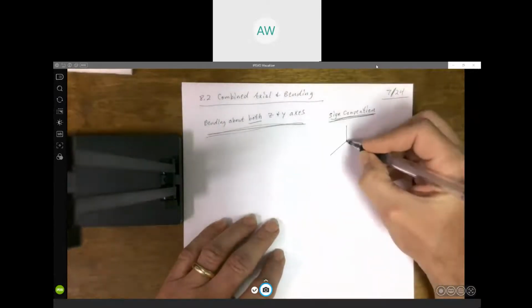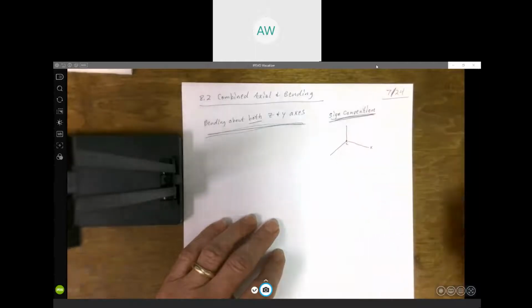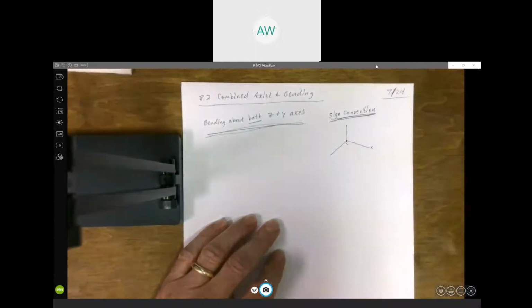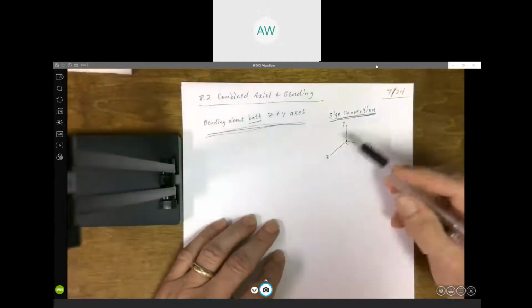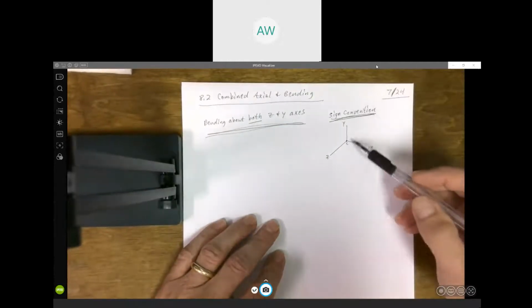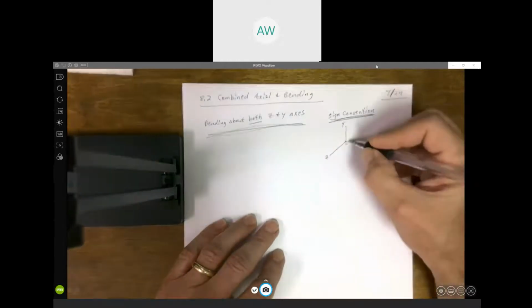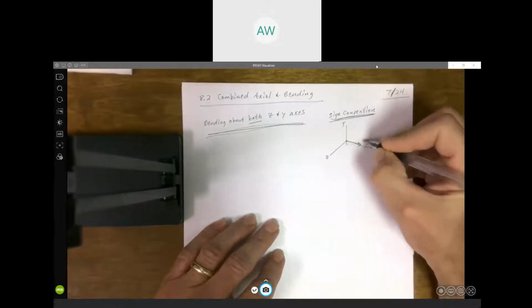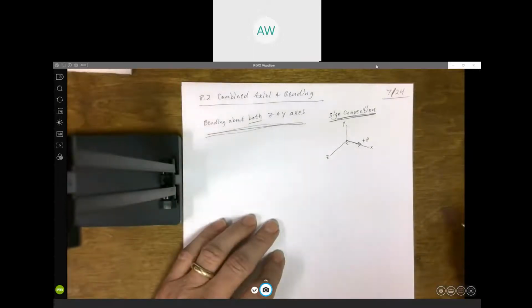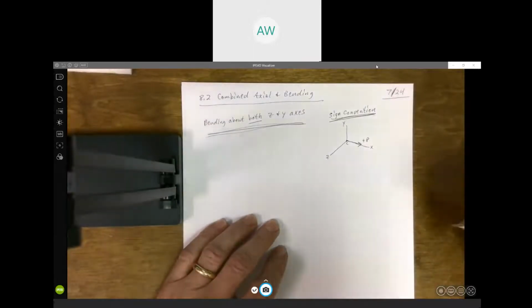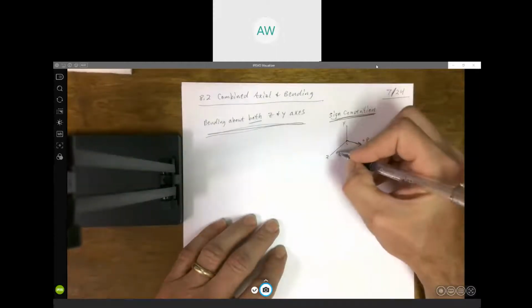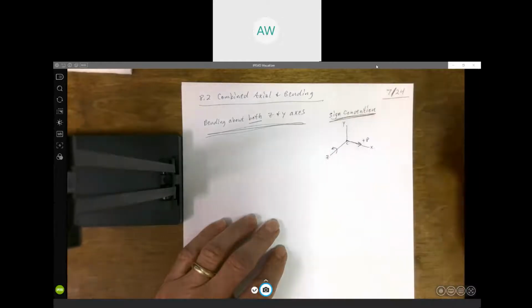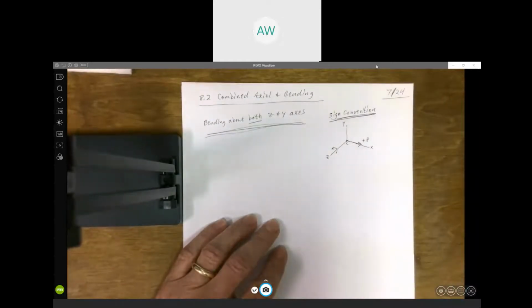And our coordinate system, remember, the origin of our coordinate system is at the centroid of the cross section. And we're looking at that cross section. Y is vertical, z is horizontal. And we, again, define a positive axial load P as being in the positive axial direction. Also note it causes tension. Right, we did this yesterday, and again, as far as the moments go, it's based on the right hand rule.